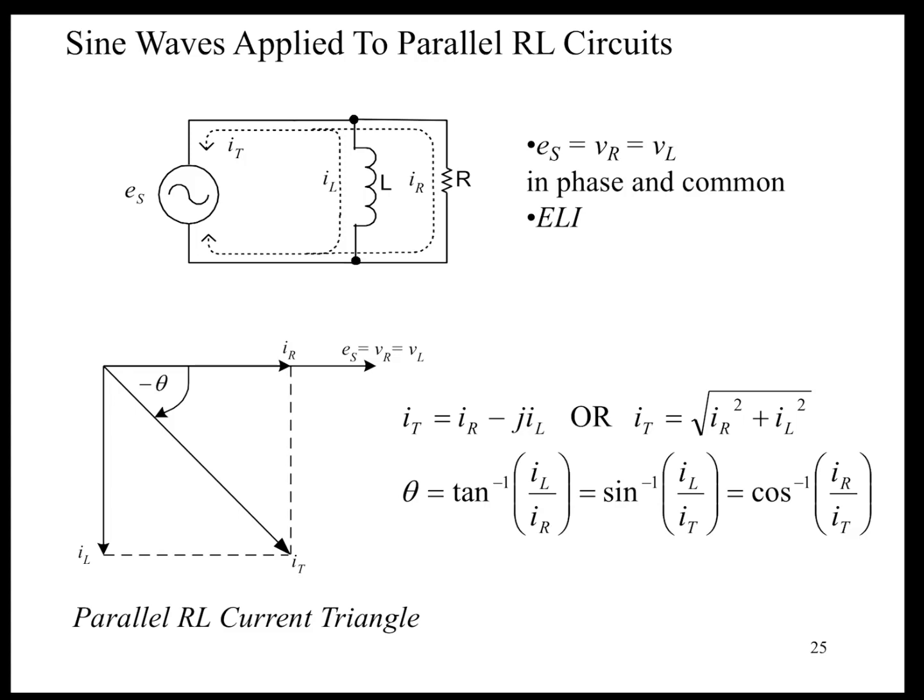So if we look at this parallel circuit, what do we need to understand? Well, we can't add these oppositions directly together like we could in series, and that's really important. If you were to tell me you could take the values here and put them together directly as a rectangular value by simply adding them together, you'd be telling me that two 10-ohm resistors in parallel equals 20 ohms, and I know no one will tell me that. So don't forget, when it comes to this, we have to come up with our total impedance by sum of the reciprocals or product over sum.